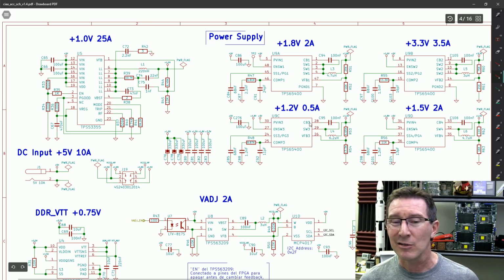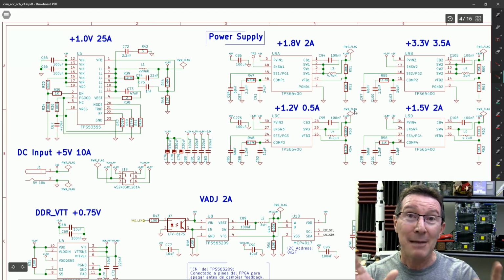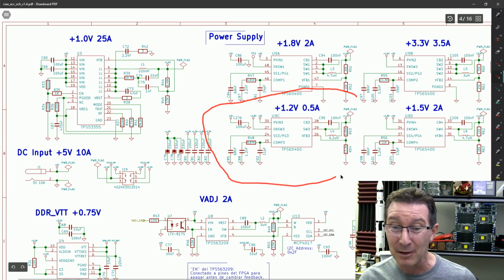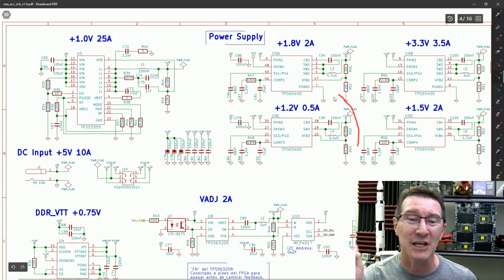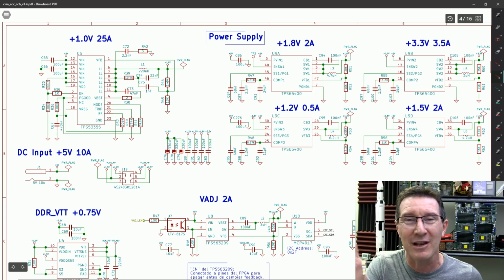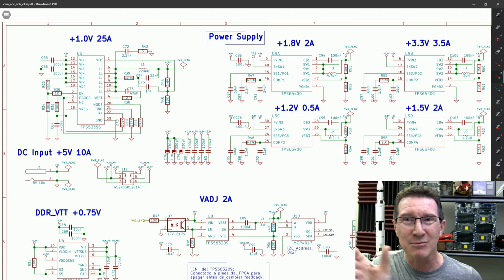Especially, what things have you optimized in designs where it was marginal? It may pay you to spend a day or two of engineering effort building up a prototype and testing it over temperature, just to verify that the value you chose can actually work, even though it might be slightly outside the margin, and you might try some tolerance resistors.